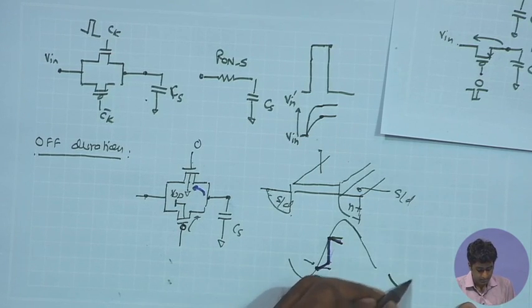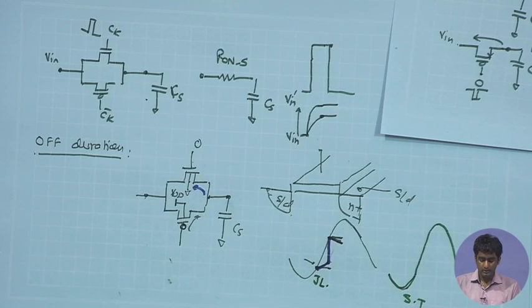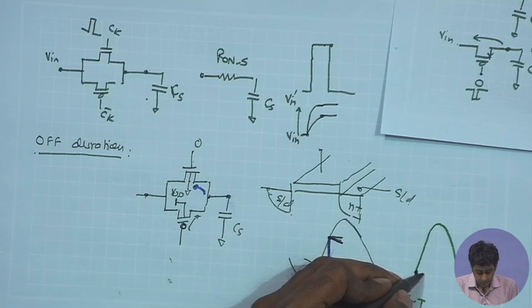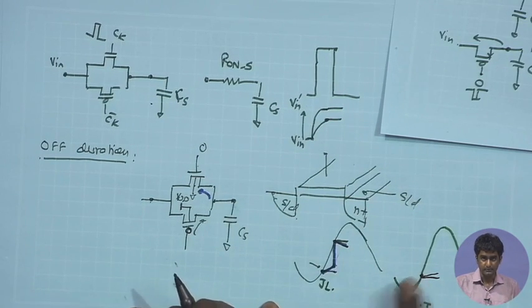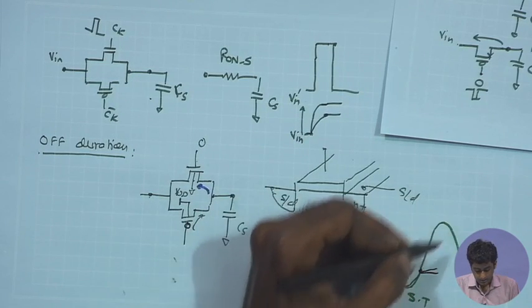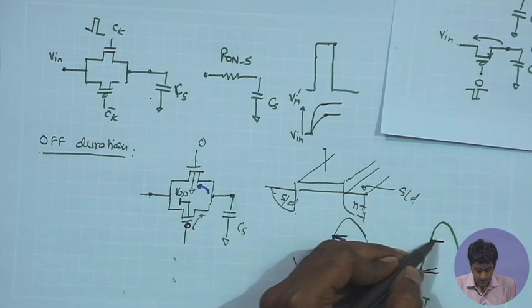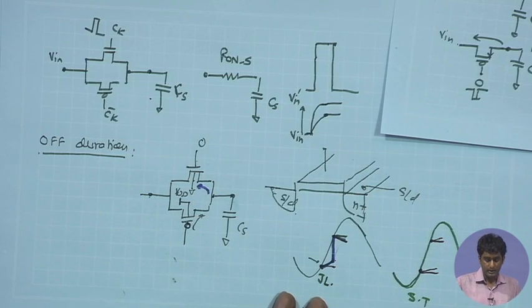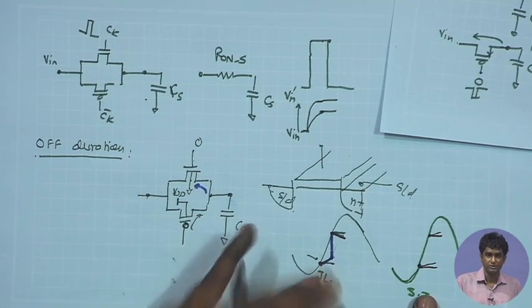If I take another example where the subthreshold leakage becomes more dominant, there if this is the sampled value at a particular instance and we want this to remain constant, rather than remaining constant, it will increase a little bit because the input signal is increasing. And likewise, if I talk about the other half, if I am sampling the data over here, here also we will have the same polarity because the input signal at the next sample is increasing, therefore it will slightly increase, and if I am going towards the downward sloping part, it will have the opposite effect. So, this is the case for subthreshold conduction, when the subthreshold conduction becomes dominant.